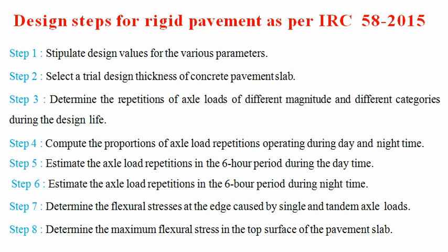So the design steps for the rigid pavement as per Indian Road Congress IRC 58, with amendments as per the year 2015, are: first, stipulate the design values for the various parameters. Second, select the trial design thickness of the concrete pavement slabs, followed by determining the repetitions of axle loads of different magnitudes and categories during the design life.